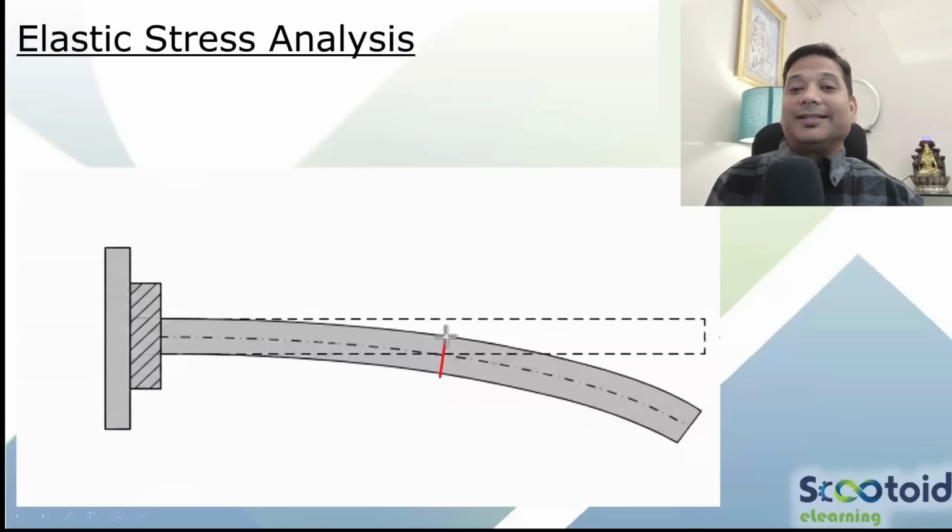In bending, you have tensile on one side, and then stresses keep on reducing. At the center point, you will not be having any stress. Then below the center, you will be having the stresses in the opposite direction. So if I take overall stresses, what is the value? It will come out 0.